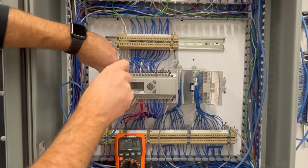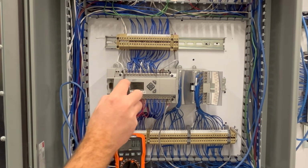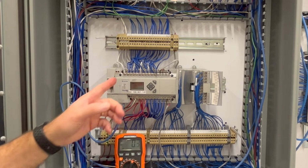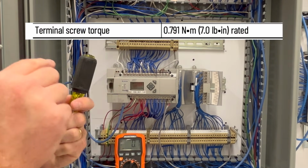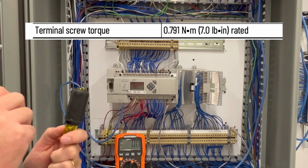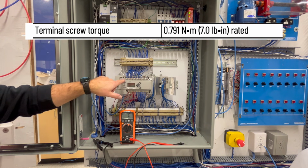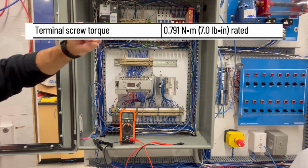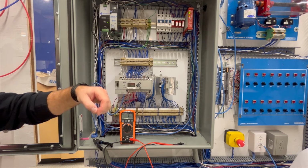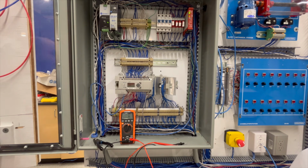And then I'm gonna go in, and if I can, I want to get a torque screwdriver, a screwdriver that has the ability to torque a screw to a specific amount of pounds. And I'm going to twist that to make sure this is good. But if I'm in a hurry to get this going and I don't have a screwdriver with the capability of setting the torque, I want to get this tight. I can use a little tug test.